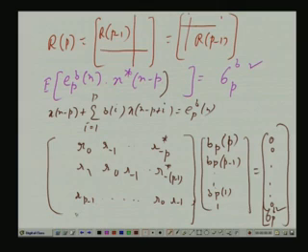You can see that this is again the same R matrix. This is the beauty: same R times a backward prediction coefficient vector of this type will give you an equation of this kind, where the top ones are 0 and the last one is an unknown but positive quantity. In the previous case, R into another vector where the starting one was 1, 1, a p1, a p2 dot dot a pp, then on the right hand side the first term was an unknown positive quantity, and all the other terms were 0.